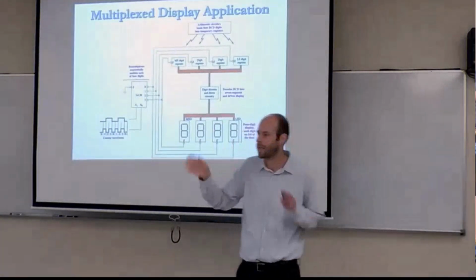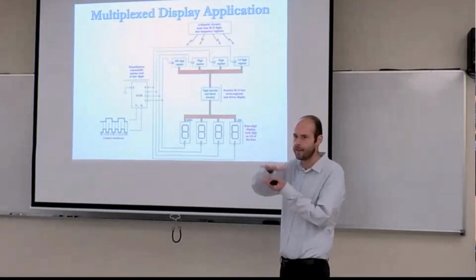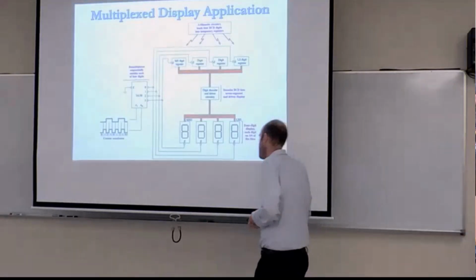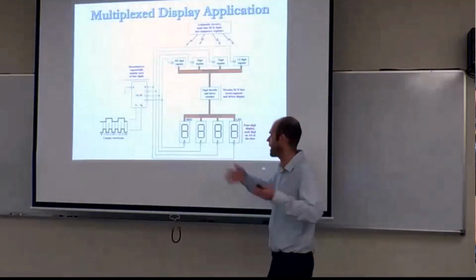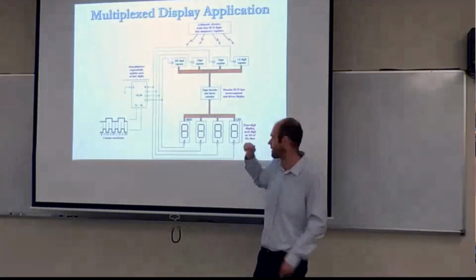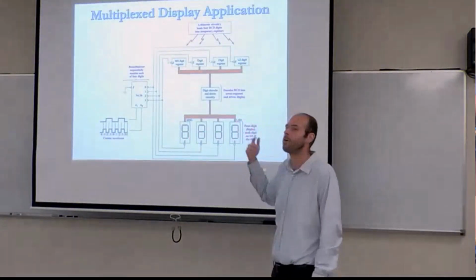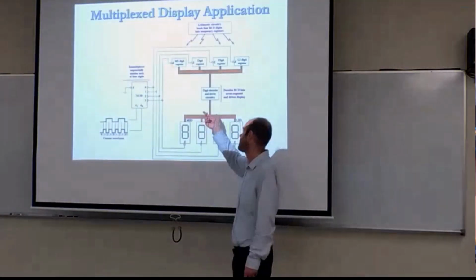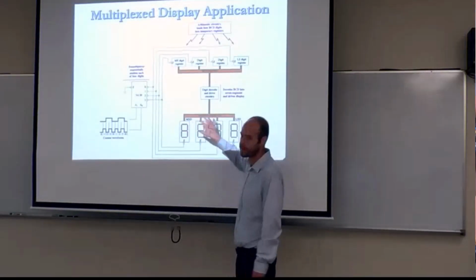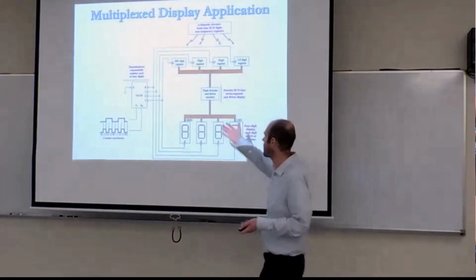And you've done various experiments with blinking LEDs in your earlier classes, where it might be blinking, then it just kind of looks like it's faded on at a low level, even though it's blinking on and off at a high frequency. You may have encountered pulse width modulation up until now. It's that idea that as long as we change fast enough, we see the averaged effect. And so when you have a bank of 7-segment LEDs, they're being multiplexed to save having to wire data bus from your controller out to the segments for every single segment. You just have one common unified driver bus.